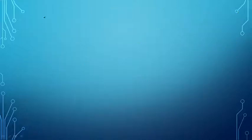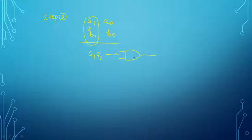Now step 3: A1 A0 B1 B0. Step 3 is the multiplication of the MSB bits, right? To multiply these 2 bits, A1 and B1, we require one 2-input AND gate. But there is a carry C1 from step 2.